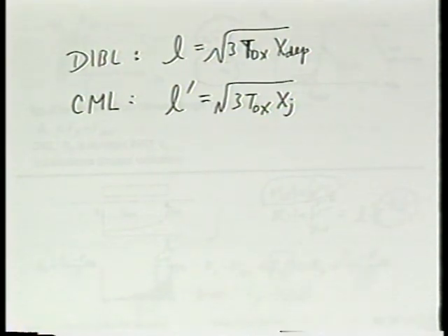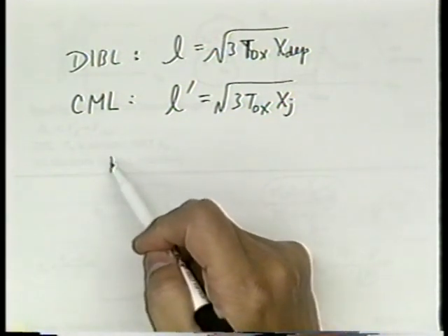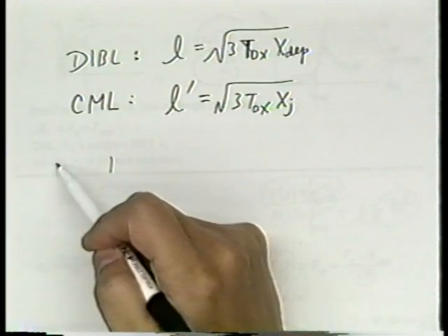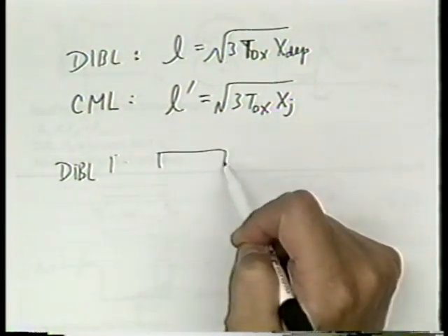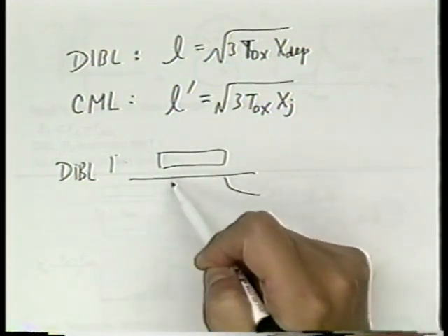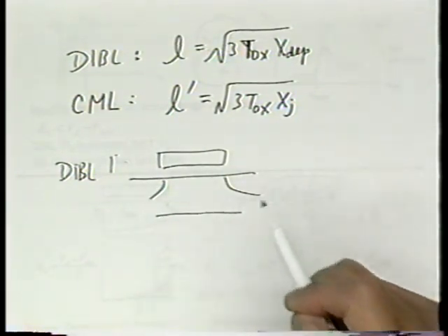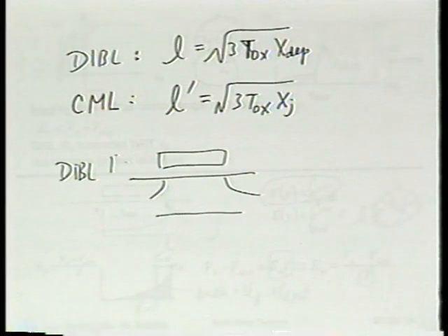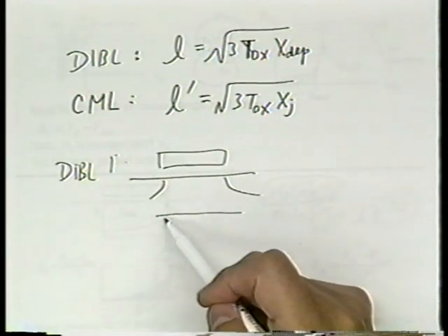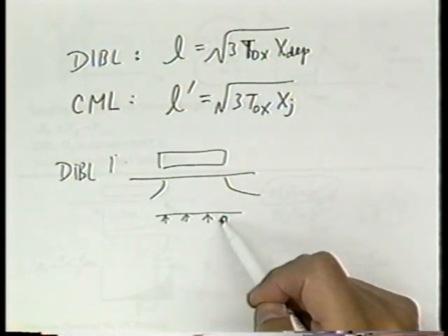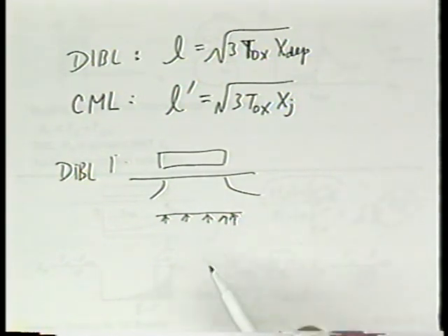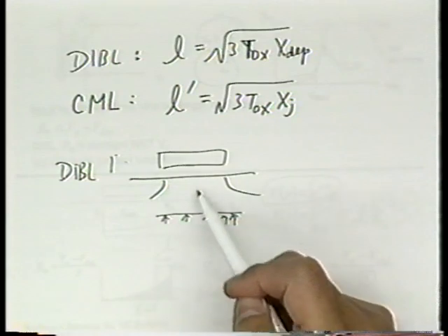What's the difference? For the dipole case, we have to look for a Gauss box which is more or less flat all the way from source to drain, and at this boundary there's no vertical field. So when we consider all the possible choices, we decided XD max is the best.